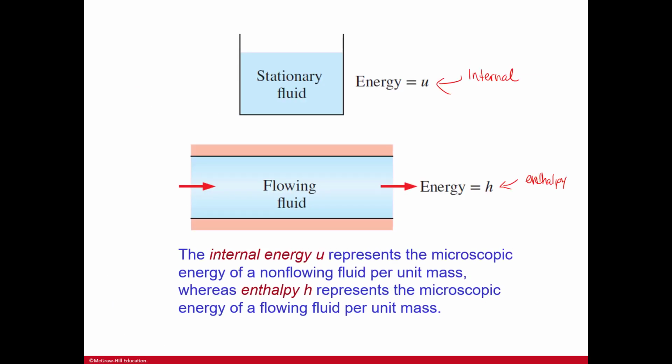So internal energy, U, represents the microscopic energy of a non-flowing fluid per unit mass, whereas enthalpy, H, represents the microscopic energy of a flowing fluid per unit mass.